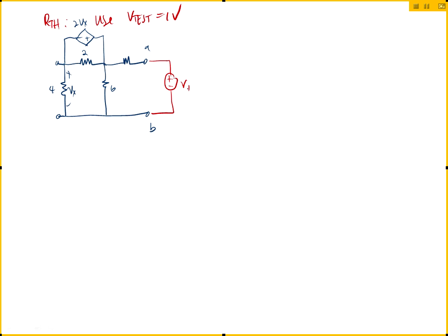Okay, so it's a voltage source now. V test of value. The value doesn't matter, so make it simple. Here's 1 volt. And as a result of applying that 1 volt source, everything on the left side of AB is just a resistor. That voltage source will develop a current through it called I test. Now our objective is to find that I test, because if we divide 1 by that I test, it should be equal to R Thevenin.